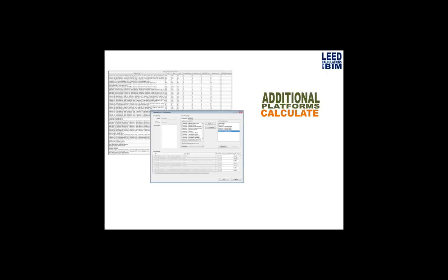rapidly renewable materials. And then you can use something like BIM link, which I'm showing up here, or you can just simply export a file from Revit directly and then link that to Excel. The benefits of BIM link are that you can format the export somewhat, but more importantly, you can push that information back into the Revit model from your adjusted Excel file. And you can also create an API to do this if you have that, but not everyone has that as a resource. So if you don't, you can do it this way.